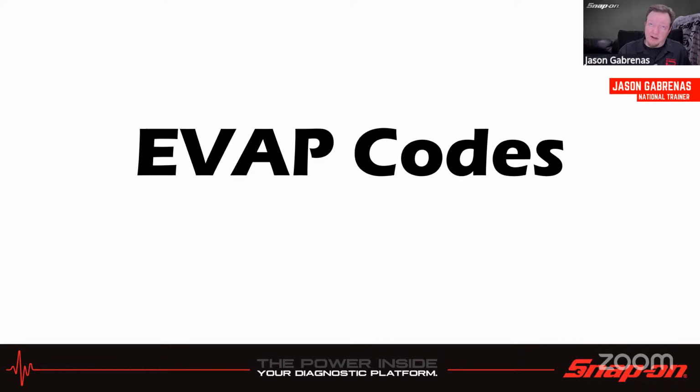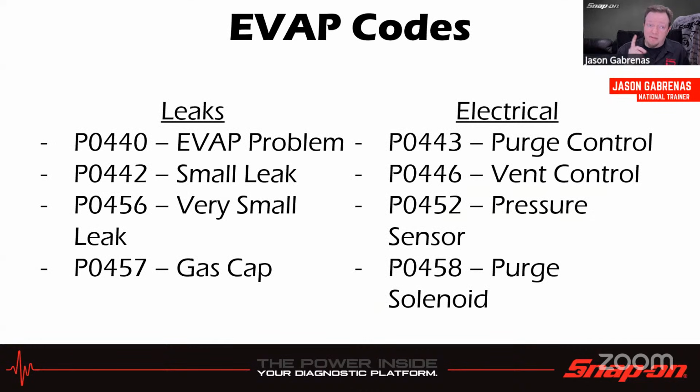When we're diagnosing Evap codes, there's two different types of Evap codes that could possibly come up. Be very aware of what your code says. What is the definition of the code? And if you don't happen to have it on the scan tool for some reason, I would look it up, because you could be fighting, oh man, it just says evap, so it must be a leak, right? However, this sampling of codes over here could be the purge control solenoid, vent controls, pressure sensor, another purge solenoid code. So it could be an electrical problem and you're chasing a leak problem. Vice versa, I guess it'd probably be less common, chasing an electrical problem when really it's a leak that you're trying to find.